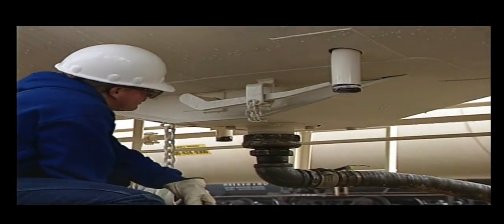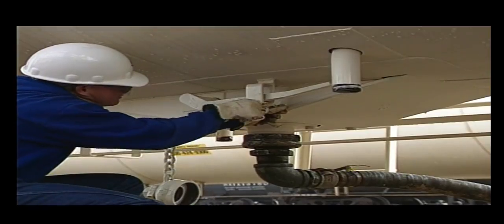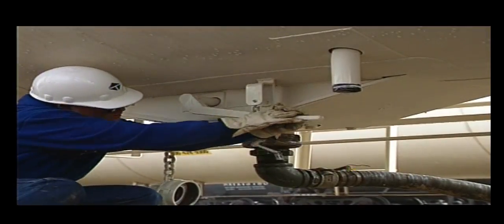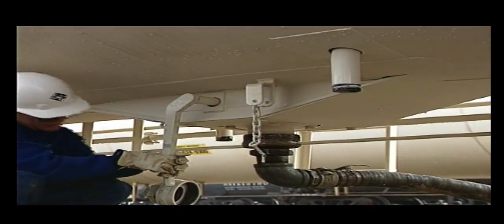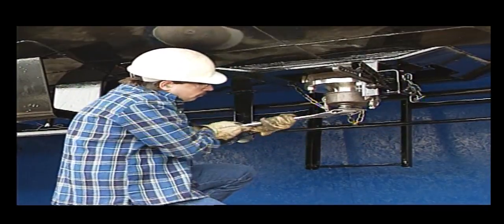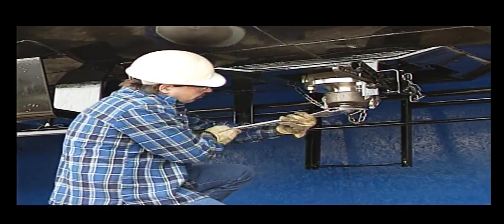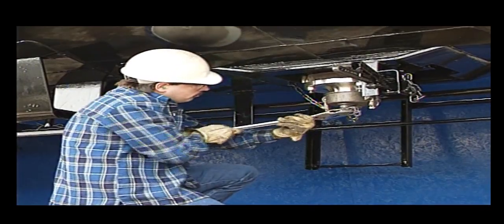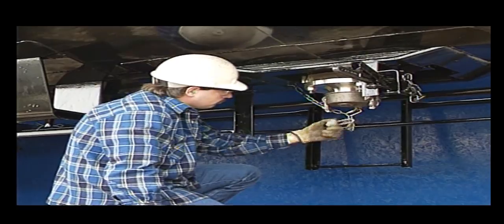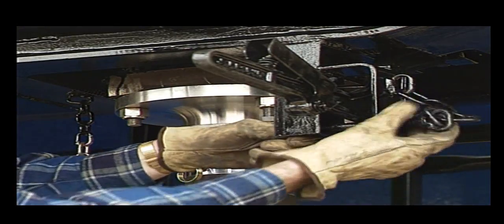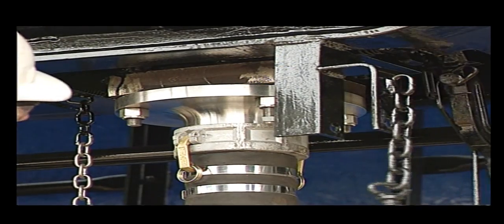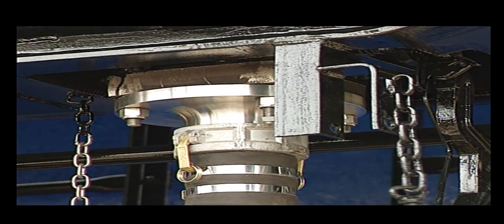The first valve we'll examine is the external ball valve. To operate the valve, remove the locking pin and move the handle downward 90 degrees. Another type of bottom outlet valve is the butterfly or wafer sphere valve. It also provides a very small profile. Most components are the same as on the ball valve arrangements, except for the valve itself. To operate the valve, first depress the locking device on the handle. Then rotate the handle downward 90 degrees.